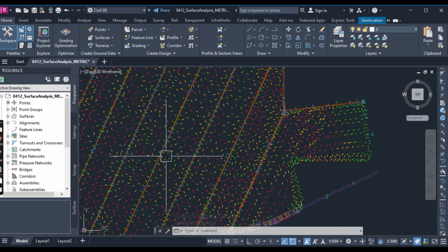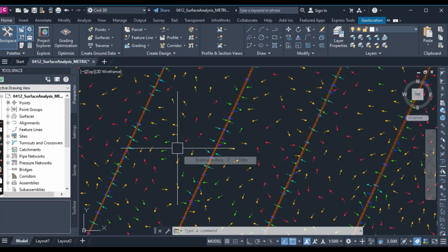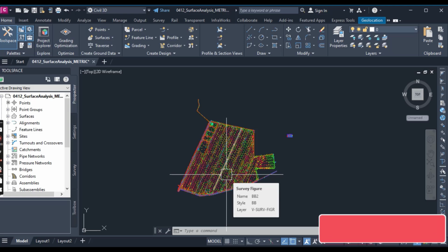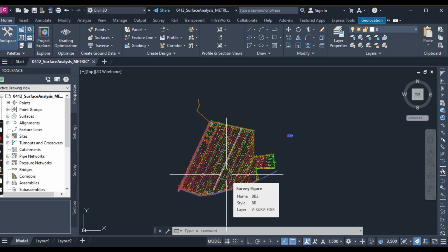You can review your drawing. Look for arrows pointing to the proposed drainage locations and you will have a simple design verification tool in Civil 3D. With this simple analysis, you can show a client the areas of their site that meet their constraints. Visually compelling and simple to produce. This is the kind of information that a 3D model makes available.